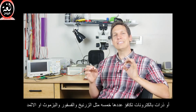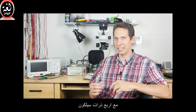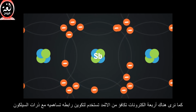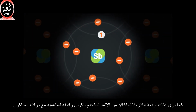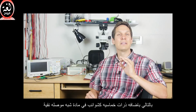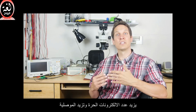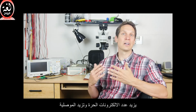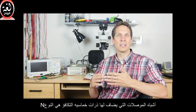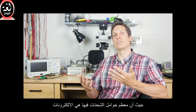To visualize this, let's examine an antimony atom covalently bonded with 4 adjacent silicon atoms. As we can see, only 4 valence electrons of the antimony atom are used to form covalent bonds with the silicon atoms, leaving an extra electron that becomes a free electron. So by adding pentavalent impurity atoms to an intrinsic semiconductor material, the number of free electrons can be increased, as well as the conductivity of the semiconductor material. Semiconductors doped with pentavalent atoms are N-type semiconductors, since the majority of its current carriers are electrons.